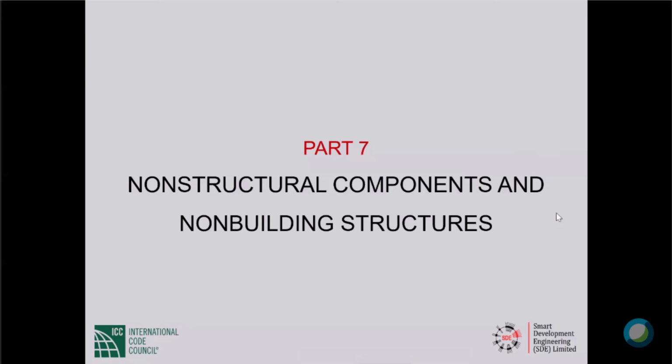And if you want to be careful, I would say keep the gravity in place. Dead plus live would be fine. Dead plus a little bit less than the full live load would be fine. But to look into load combinations is not something that is called for. In what condition would we consider a shear wall to be cracked, and when uncracked due to analysis? That is very easy to figure out. You run an analysis based on whatever assumption. If the bending moment that you calculate is more than the cracking moment, then the shear wall is cracked. If it is not greater than cracking moment, then it is uncracked.